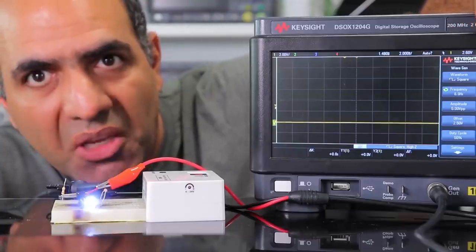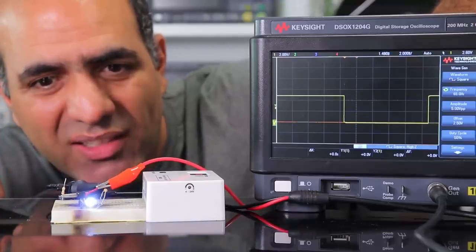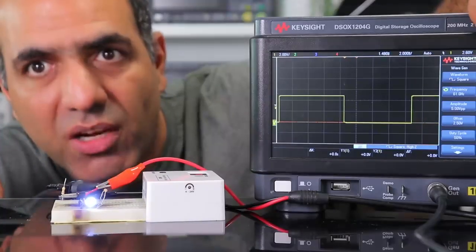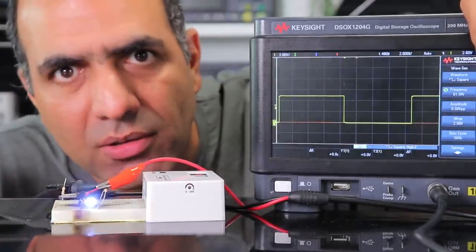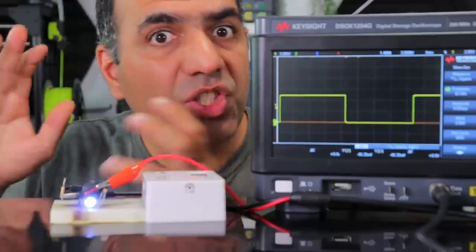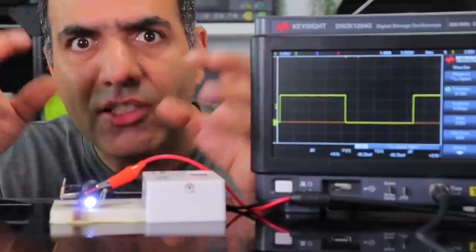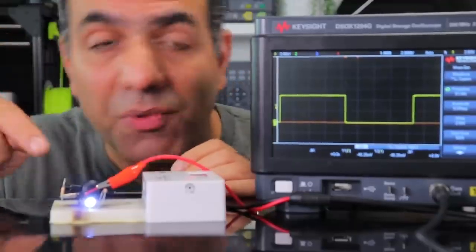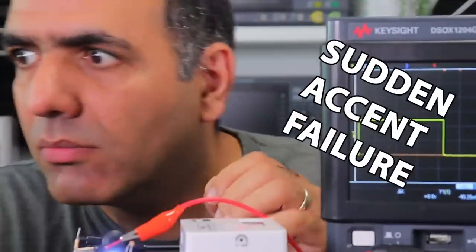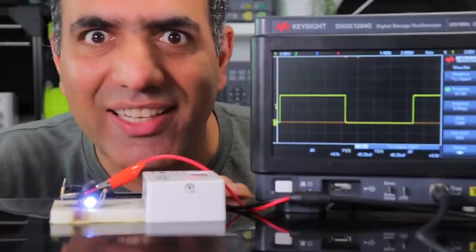Somewhere above 60 Hz, we stop seeing it flickering and it becomes continuous. But as you may have noticed, it's half bright now. This is because, same as when I was driving the LED with the AC line, although we don't see it, the LED is only on half the time, so the average brightness is dimmer. We can use this technique to adjust the brightness of the LED.